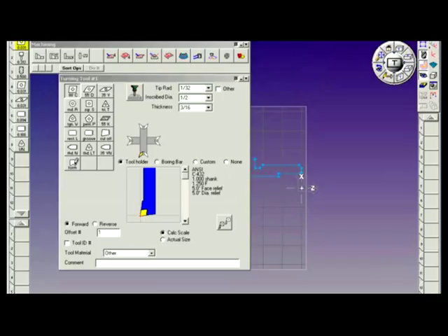The 4 represents the inscribed diameter in units of 1/8 of an inch. 4/8 equals 1/2. The number 3 is the thickness of the cutter in 16ths, 3/16. And the 2 is the tip radius in 64ths. 2/64 equals 1/32. When we select catalog criteria, we're able to see the tool holder.